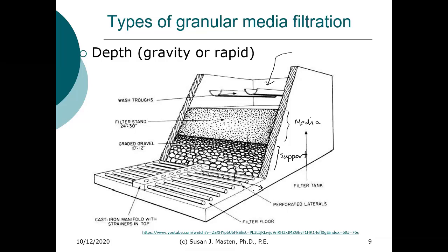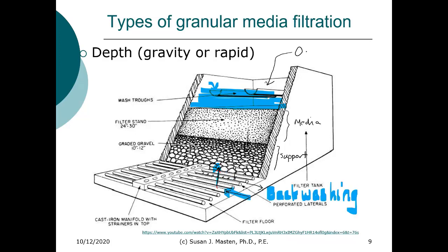During backwashing, the opposite happens. So now we're going to pump water back upwards. We'll fluidize this bed. So now the water layer will be up over these laterals here, so the water flows into the lateral. So this is during backwashing. This is during operation.